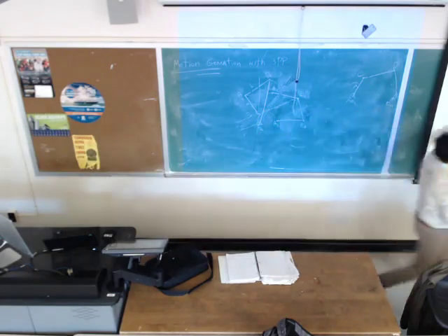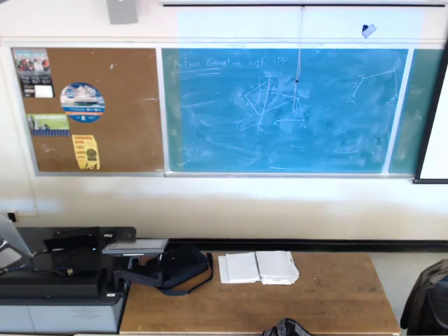Here you can see a better drawing. I have A1, B1, A2, B2, and A3, B3. I draw the perpendicular bisector between A1 and A2 because I know that O2 should have the same distance from A1 and A2. At the same time, it should have the same distance from A3. So I draw the perpendicular bisector of A3.